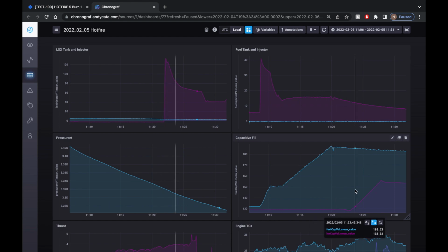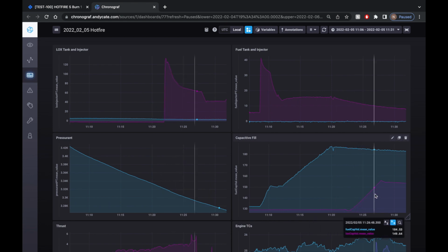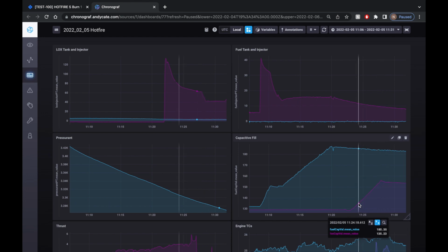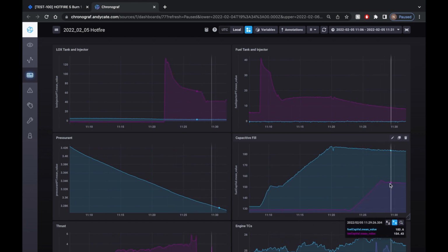And that's also the reason why we fill LOX second, after the fuel, because it's boiling off at a much faster rate, and we're losing more liquid oxygen per minute or per second. We want to save as much LOX as possible, and that's why we fill LOX after the fuel, just to decrease the amount of time between filling the LOX and actually starting the flow.